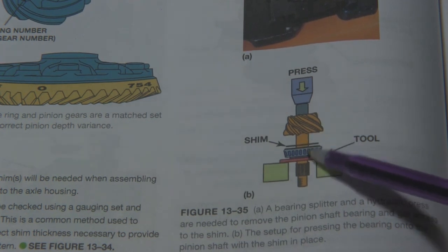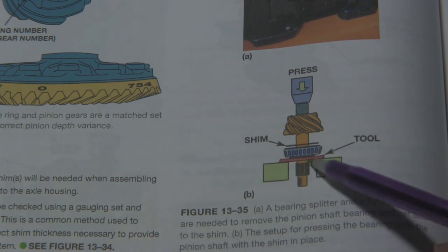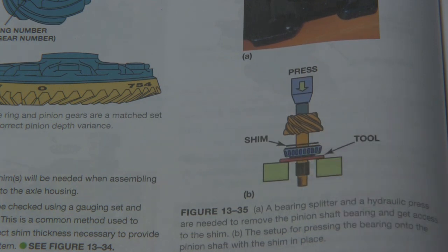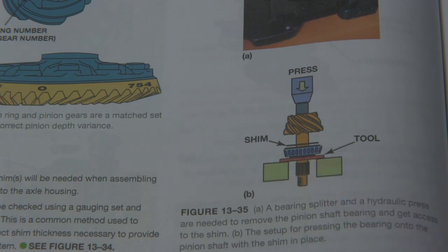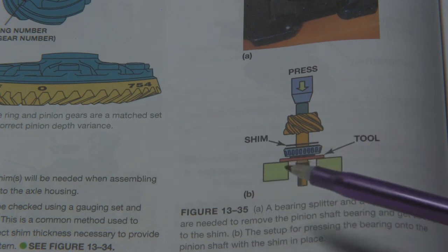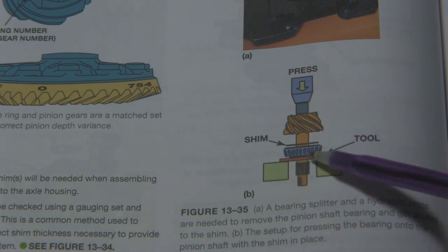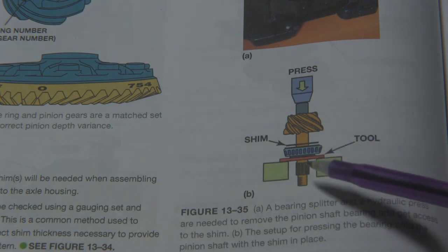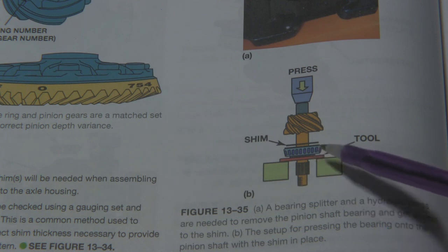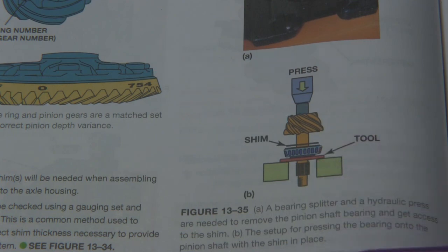And what you're going to do is, for the pinion bearings and also for the carrier bearings, you're going to cause them to not have a press fit, which is going to be just for setup only. And then you'll set up the differential with all these bearings in place, and then you'll check your contact pattern. And if you're happy with the contact pattern, you'll take it all back apart one more time and put the actual new bearings press fit onto the shaft. If you're not happy and you have to change out shims, it's not a big deal, because you just disassemble, slide the bearing off, change the shim pack, slide the bearing back on, and recheck your contact pattern.